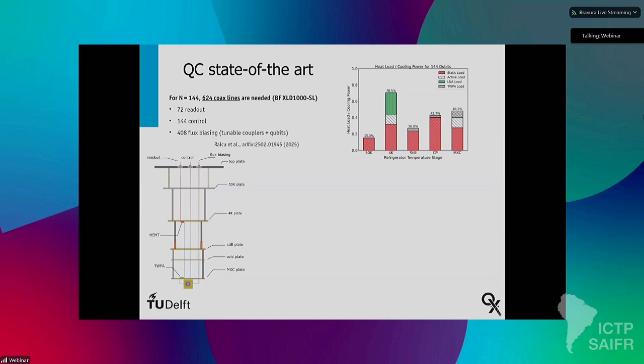And one idea that the field has been pitching quite a bit recently is using optical fibers for this, right? You can reduce the passive heat load by orders of magnitude by using, instead of metal wires, essentially glass that has no thermal link to the cryogenic environment. Then you can also multiplex these systems, so you don't have to use a single fiber for each qubit or for each line. You can run multiple channels per fiber. So this is really promising to scale.